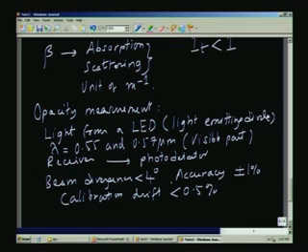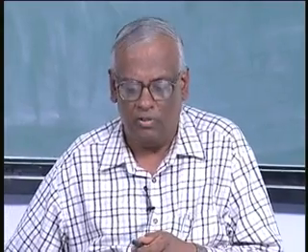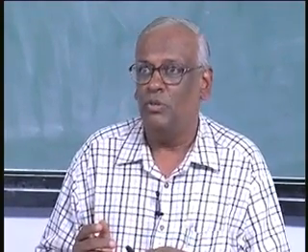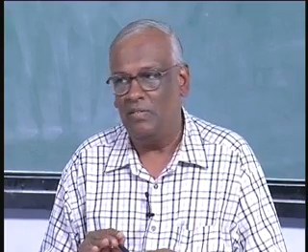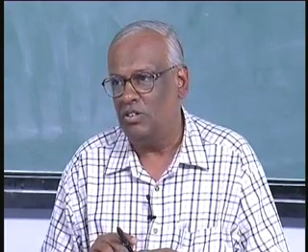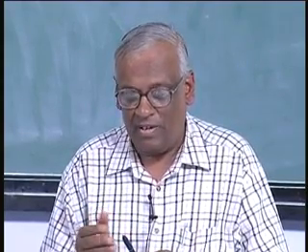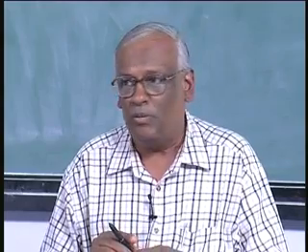So, we use a specific wavelength. Therefore, this is very important to remember. If you use a different wavelength, the properties of the medium will be quite different. Therefore, when you are quoting the numbers, one must immediately see which instrument has been used, and what is the wavelength which was used in that particular instrument. That is very important, because opacity is not independent of the wavelength of the source of radiation. If you use, for example, a helium neon laser, which has a higher wavelength than what I have given here, it will give you a different opacity.